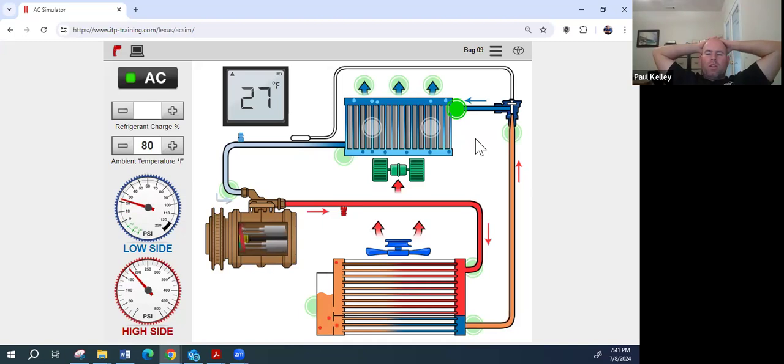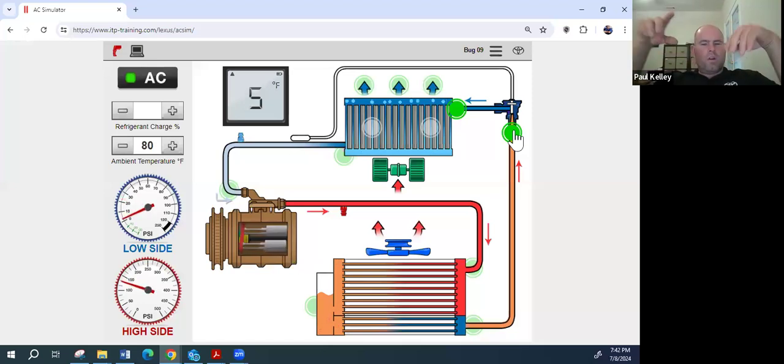I told you a story about this already. Remember? In the station wagon with the family. Exactly. That moisture comes and hits that TXV, ices the needle over, causes a big restriction. The low side drops too low. The high side for a second would probably spike too high. Right? Because it's a restriction. Don't you think the high would be too high and the low would be too low? And you're right, it would be for a second.